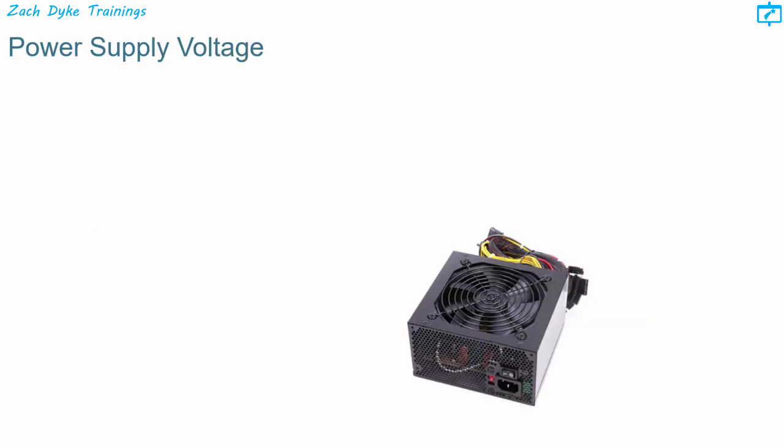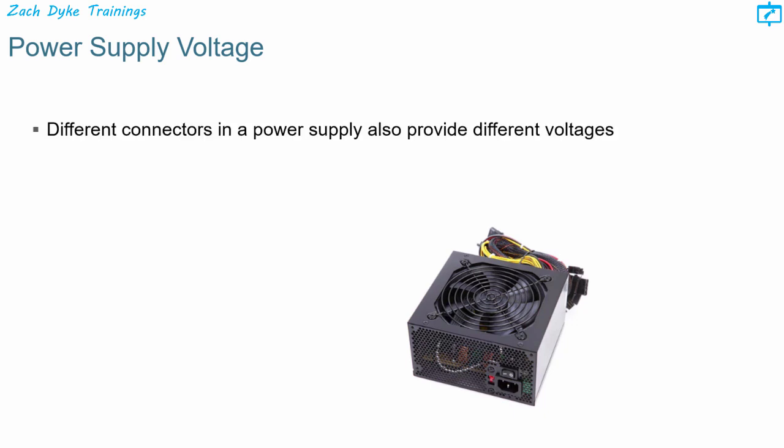What about the power supply voltage? When you have different connectors in a power supply, you also need to provide different voltages. The most common voltages that are supplied are 3.3 volts, 5 volts, and 12 volts. The 3.3 and 5 volt supplies are typically used by digital circuits, while the 12 volt supply is used to run motors in disk drives and fans.